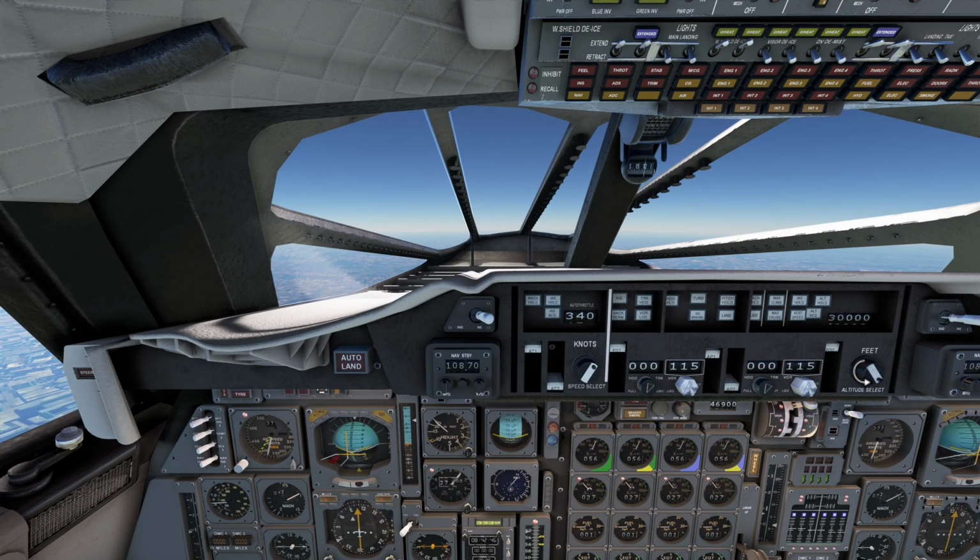Altitude new 45,000 feet. Alt acquire for the moment. We go to max climb afterwards. Auto throttle off. Full power set. Afterburners are now in use. We're going to leave full power for the rest of the flight, very unusual for a plane. We're just going to turn off the afterburners, as we said, at Mach 1.7.